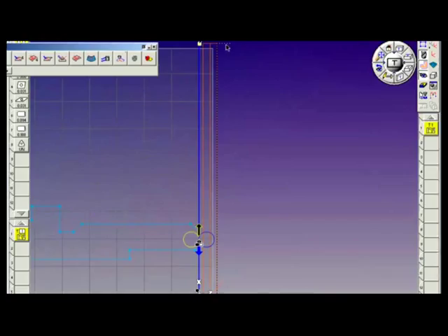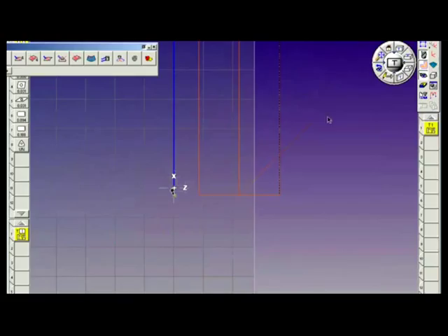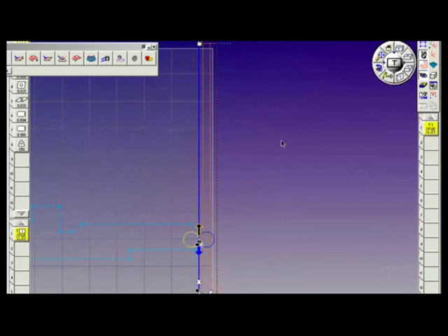The white dotted lines are rapid approach moves. The solid orange are feed moves within the tool path. The dotted orange are rapid moves within the tool path. If we were to see any solid white lines, they would be feed approach moves. This move at the end is where we're doing our auto clearance move in X and Z before we return to home. Previous view shows us that once again.